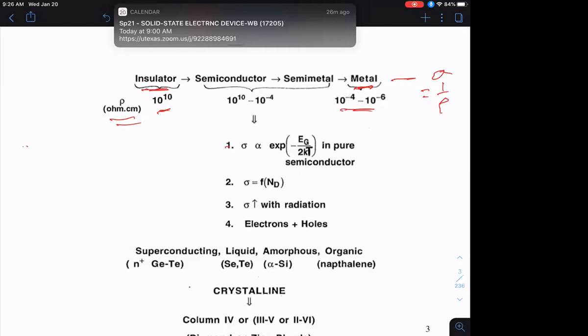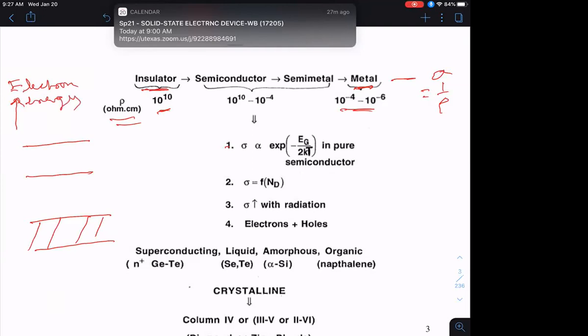As an introductory concept, when I talk about a band diagram, I talk about energy levels that electrons can have in a semiconducting crystal. So this is electron energy plotted on the vertical scale as a function of position in that semiconductor device. So think of a transistor. At every location, I can plot what the electron energies are as a function of position.